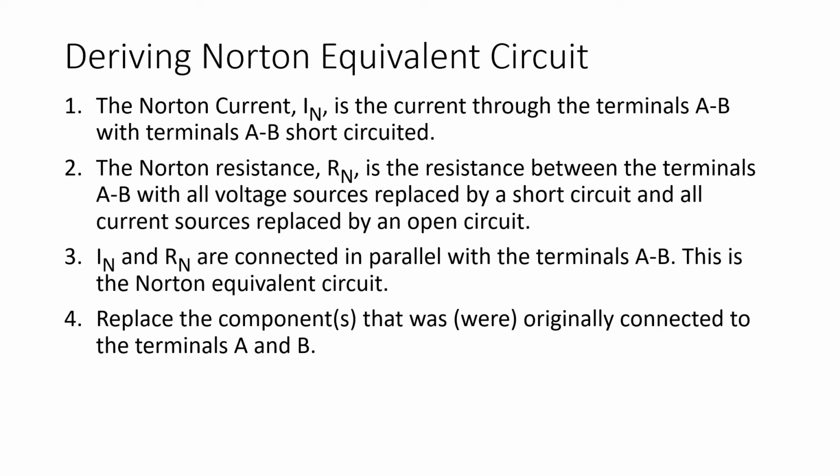Step 3, connect IN and RN in parallel with the terminals A and B. This is the Norton equivalent circuit as seen in Figure 1. Then replace the component or components that were originally connected to the terminals A and B.